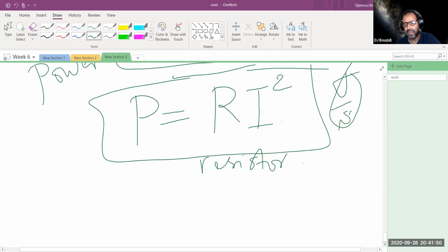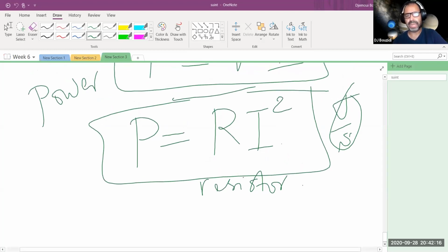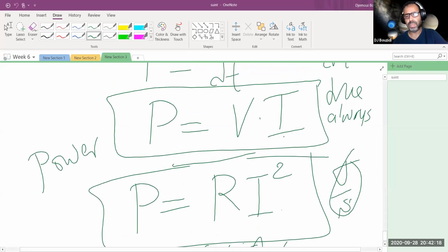We have to find what happened to the energy for a specific circuit, and we're going to be calculating the energy, knowing only the power, so we have to integrate. So if the circuit is open for an infinite amount of time, we have to sum it from 0 to infinity, from the time we close the circuit to an infinite amount of time. So basically to forever. So this is in terms of the power. This is also another key relationship. Actually, both of them are. This is true always. In the case of the resistor, this is expressed as Ri squared.